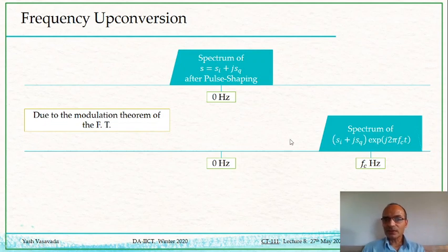Now, there is one other property of Fourier transform which was given to you in the reading assignment, which says that a signal which is real valued in the time domain, meaning it has no imaginary component, will be complex conjugate symmetric in the frequency domain, which means that there will be a symmetry in the frequency domain.